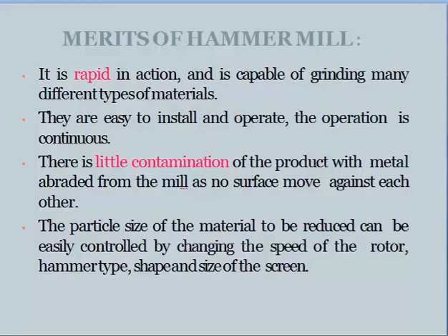Now, merits of hammer mill. It is rapid in action and is capable of grinding many different types of materials. They are easy to install and operate. The operation is continuous. There is little contamination of product with metal abraded from the mill, as no surfaces move against each other.